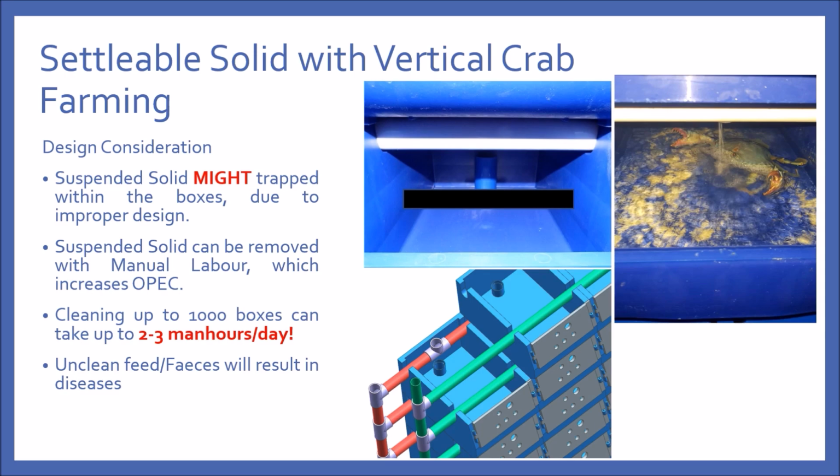However, typically cleaning will take up 2 to 3 man-hours on a daily basis, and each box will require 45 seconds to 1 minute to clean. Note that we do not clean each individual box every day, and we only clean out those that are dirty or have some solids that have accumulated. Note that solids that accumulate in your systems would often result in deteriorating water quality and often result in diseases.